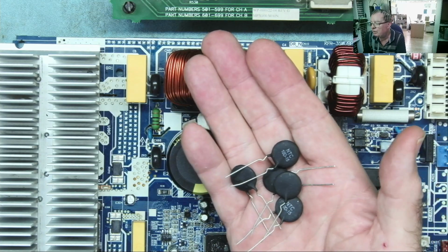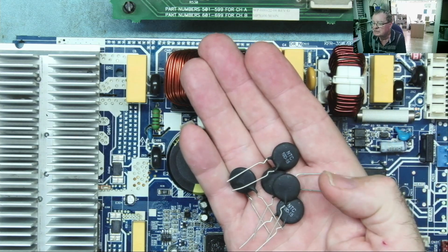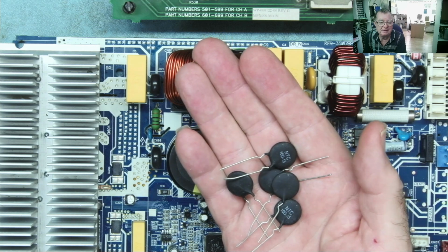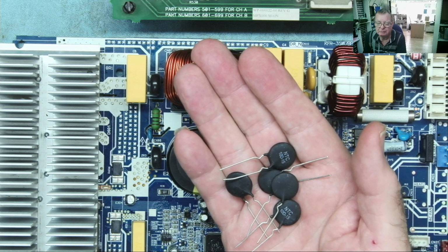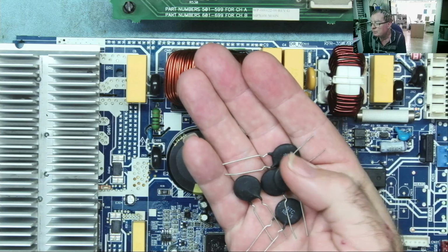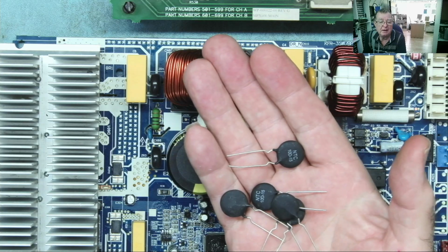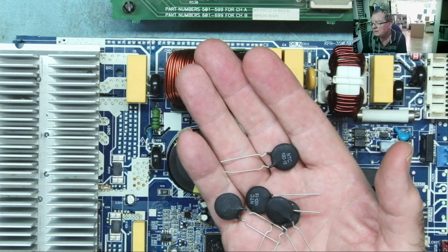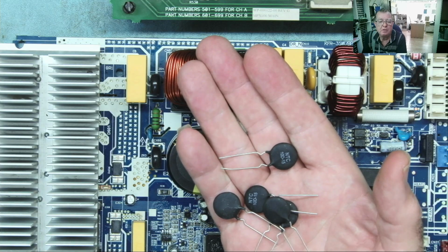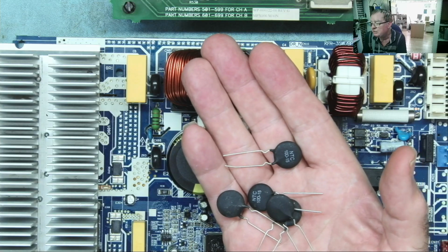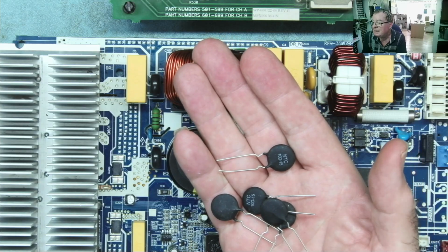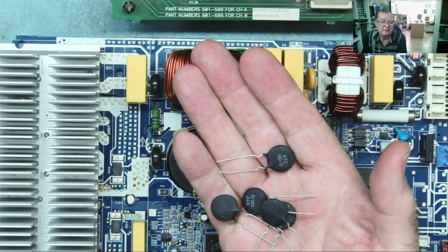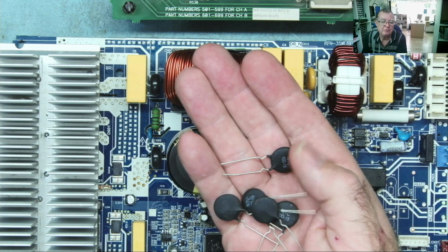These therefore are subject to a fair bit of stress, especially for items that are being connected and disconnected from the mains on a regular basis. They will fail eventually, and they go open circuit. Sometimes they actually blow up, crack open, but they go open circuit. These do not fail in any other sort of way. So have a look for these, especially on things that will not power up. They're dead, as though a fuse is blown.